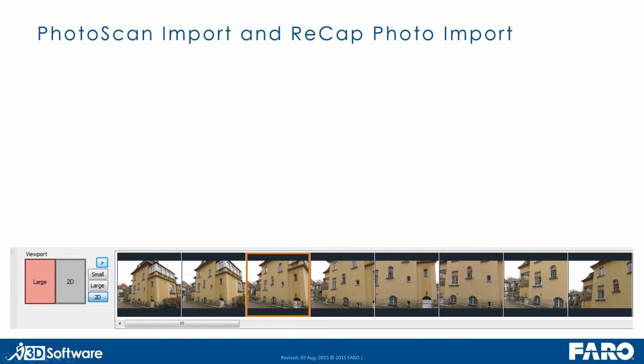The tools that we are using to get those results are first of all, you would need to orientate images, and Photoplan does provide tools for manually orientating photographs. You would need 9 control points per image.